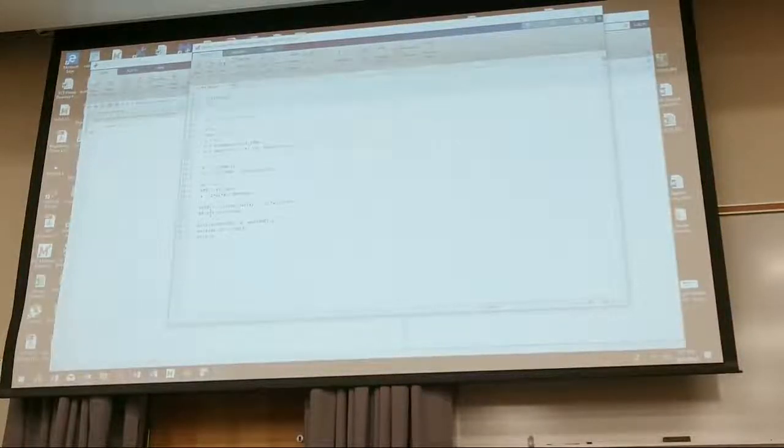Then I go ahead and I say, now, this is how you take the DFT. Well, I'm sorry. Once I have that, do you see that DFT equals FFT of x of n? You all see that? That's literally taking the DFT of the signal, the e to the minus at sampled at those points. Remember, that's a vector, and it has 2 to the n points. And it's literally taking the DFT of that. If I just presented that information, it would be meaningless to you. I'm going to do that, but I'm just showing you what this code's about.